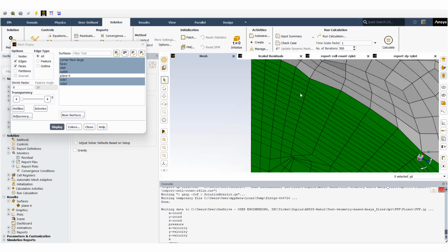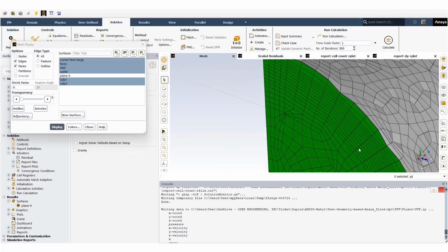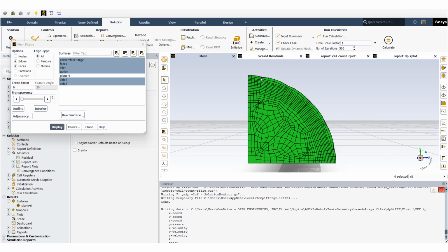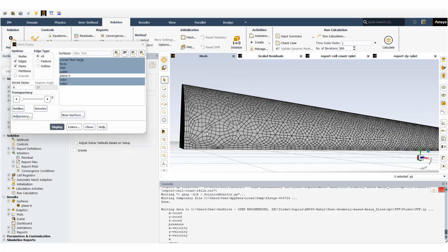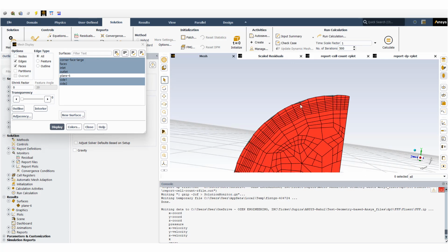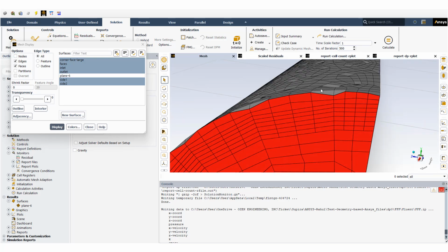You can see that here. This is for the inlet. You can see what's happening, like a bumpy shape at the inlet. And it could be similar for the outlet. Look at the outlet. These are initial nodes. For example, this segment is quite large in the initial mesh, and it wanted to create other nodes to produce the curvature from the background mesh, from the surface mesh, from auxiliary geometry. That's why it created the mesh like this.